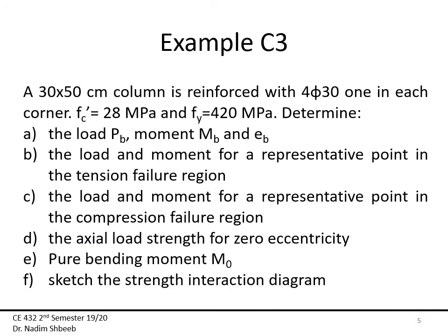So I have a 30 by 50 centimeter column. It is reinforced with 4 phi 30, 1 in each corner. F prime C is equal to 28 megapascals. Fy is 420. Determine the following. I want you to find the balance load, balance moment, and balance eccentricity. Okay, that's the first requirement.